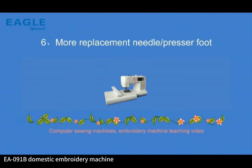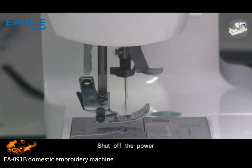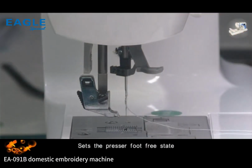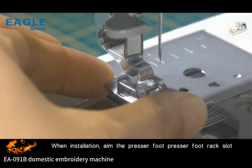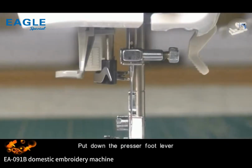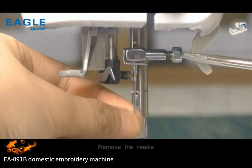6. Replacing the needle / presser foot. Shut off the power. Press the foot spring switch on the shelf to set the presser foot to a free state. When installing, aim at the presser foot rack slot and put down the presser foot lever. With a screwdriver, loosen the needle fastening screw. Remove the needle.